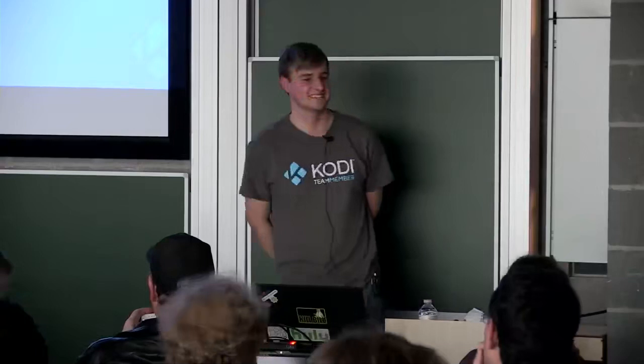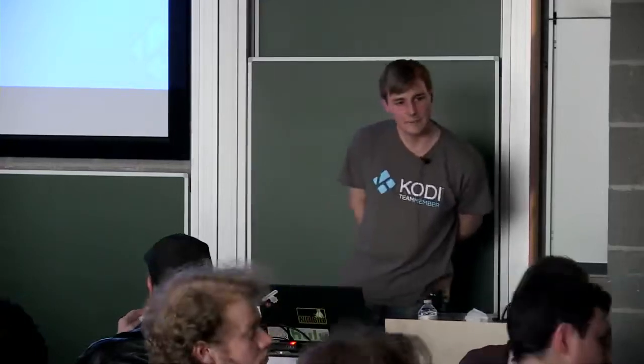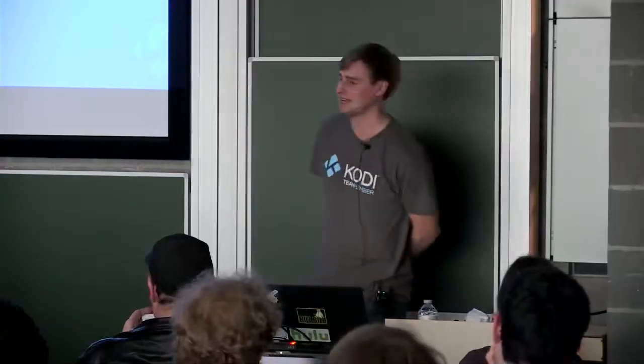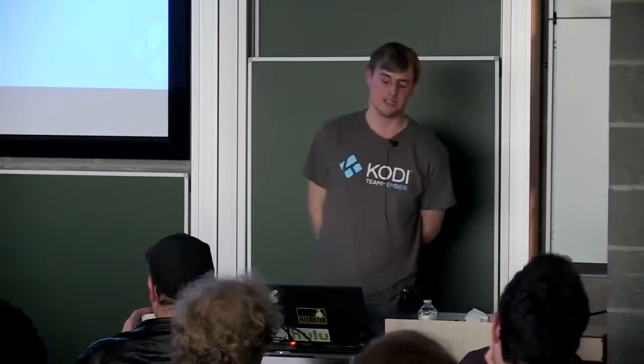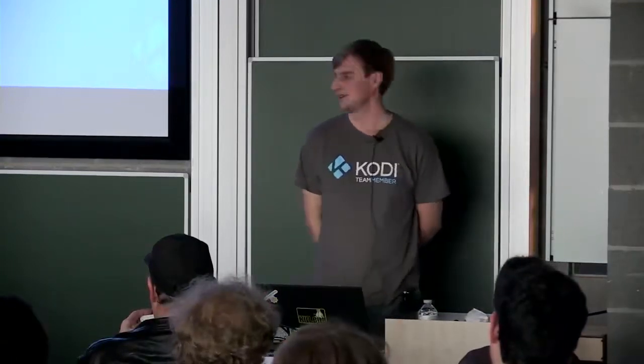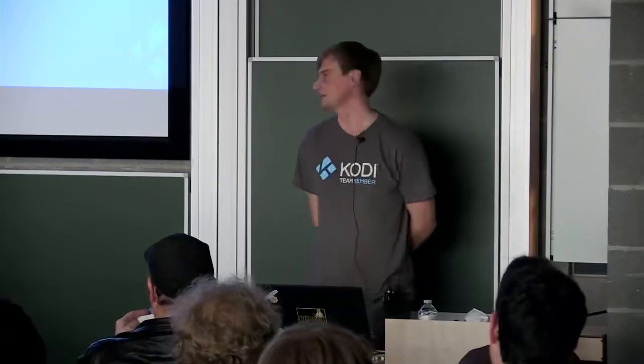Any benchmarks before and after? I don't actually have any benchmarks other than the fact that without the V4L2 stuff in Kodi, it just won't run on platforms like IMX6. Using the proprietary method works, but it's basically doing the same thing. So you could play standard def playback using software decoding, but here you actually can play full 1080p 60 frames.